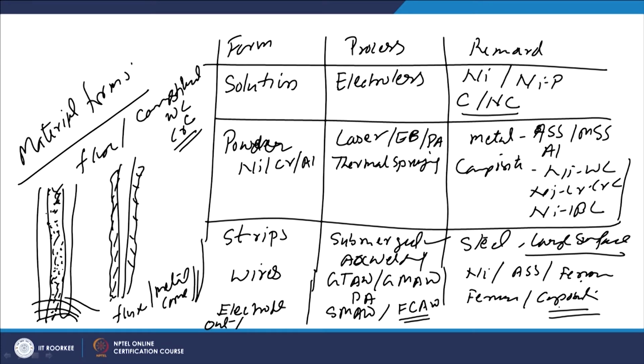and where these kinds of methods can be applied, like all those processes where an arc is to be established, like in shielded metal arc welding, gas tungsten arc welding, submerged arc welding, flux cored arc welding. In all those cases, it is necessary that the workpiece has enough electrical and thermal conductivity, so that the arc can be established. While in case of laser welding, it is not necessary. In case of electron beam welding, it is not necessary that the workpiece is electrically conducting.